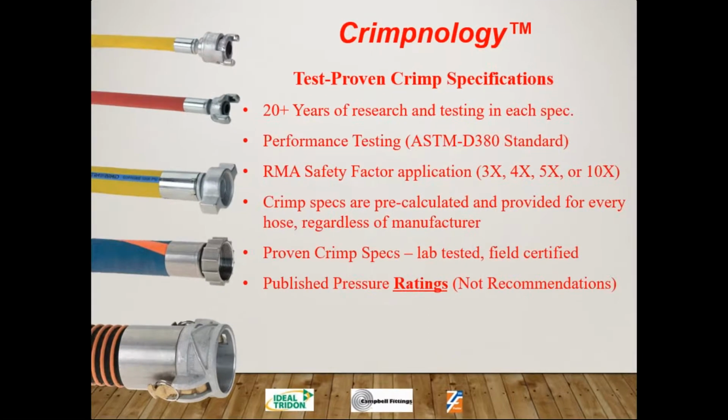So Crimpnology, 20 plus years of research and testing in each spec. All of our testing is done to ASTM D380 standard with an RMA safety factor application of 3, 4, 5, and 10 times. So 10 times will be for steam application. 3 times is typically for a low pressure 150 PSI water application. For the most part, everything that was in the previous slide is typically a 4-to-1 safety factor. It's pretty much the standard for most of our fittings.